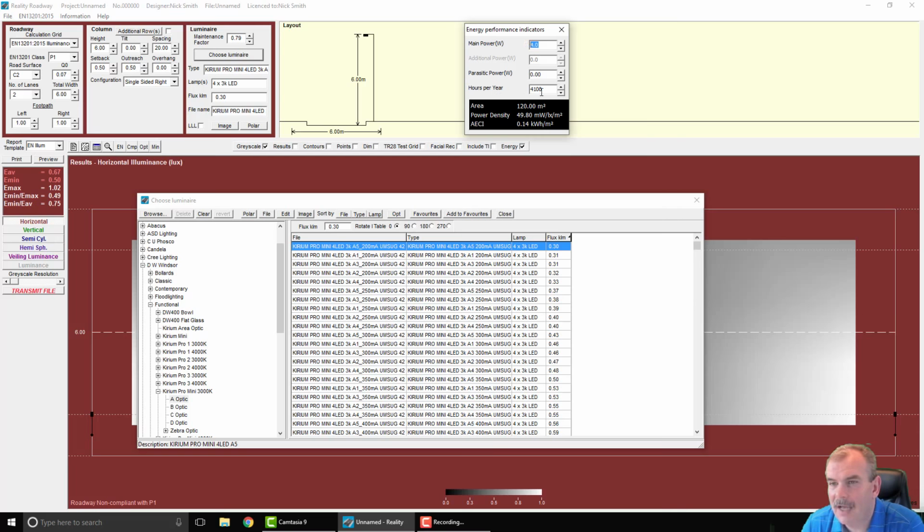Now, for the AECI, you need to set up the watts, the hours, the burning hours per year for the area where the fittings are going to be. And obviously, I'm based in the UK in the Midlands. It's about 4078 is the energy, which is why it's set to 4100. It's about the right figure, but you would obviously need to get the figure based on the switching regime and the location you are in the country, and that will give you the right calculation.